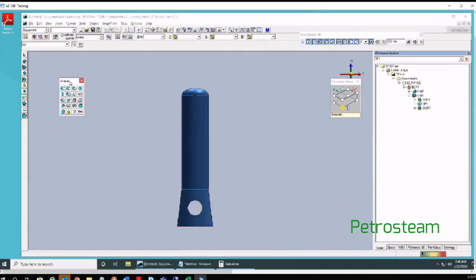What is the next option available? We have added a datum point required for nozzle placement. We can add a nozzle now. We will see the next option, the place nozzle command. Normally, to add any nozzle, you have to start by selecting the datum point as the parent.